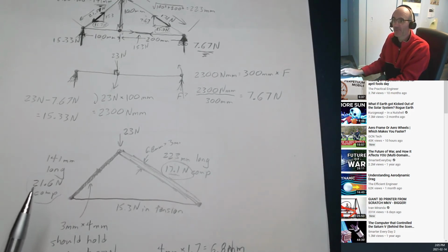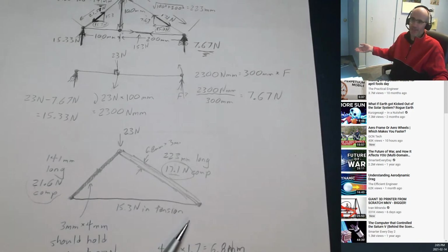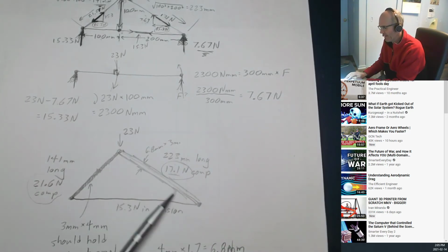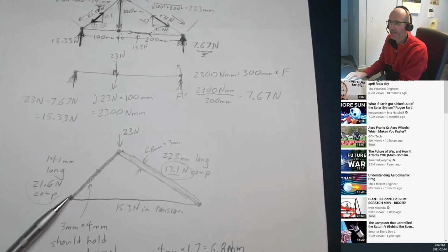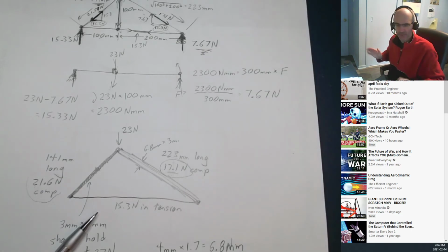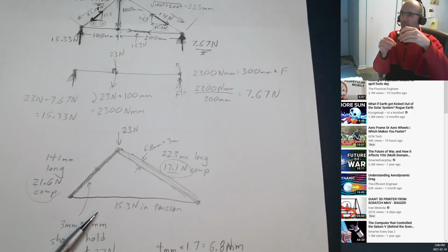It doesn't have to be strong at all. Well, it has to be strong enough to support the load, but you don't have to worry about buckling when it's in tension. Buckling loads really matter, okay? Buckling loads really matter because they are compressive loads. And things, when you compress them, pop out to the side. Take a ruler, press on the end, pop out to the side. Now, it always pops out in the skinniest direction, okay?